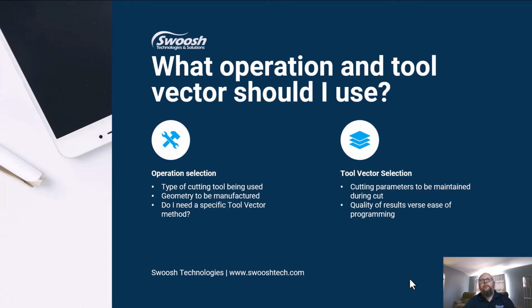Well, then I'm going to probably be doing something more along the lines of interpolate vector. There's more effort from a programming perspective, but also we can expect better results. Now, if quality is not the primary objective, maybe we just need to make a shape. Maybe it's not a tight tolerance. It's not a functioning surface that needs a lot of care done to it. Well, then we don't have to spend so much time. We're just worried about executing that geometry and moving on to the next problem.